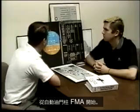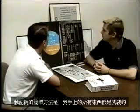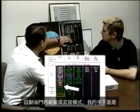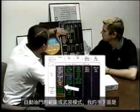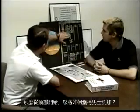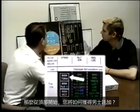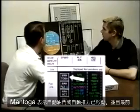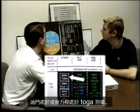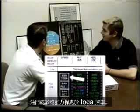Start with the auto throttle column FMAs. An easy way that I remember it is that everything above my hand is arming modes of the auto throttle, and below my hand is engagement modes of the auto throttle. So starting with the top, how would you get MAN TOGA? MAN TOGA means that the auto throttles or auto thrust is armed, and the most forward thrust lever is in the TOGA detent.